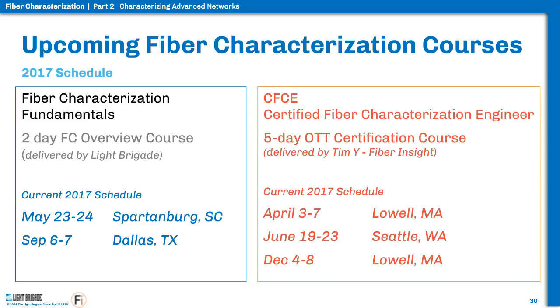I could also choose to do the ORL measurement using my OTDR and not an ORL meter. So I could skip the ORL measurement in a purist sense. I could run my OTDR measurement and get ORL and reflectance data. Keep in mind that with an OTDR, you're able to get ORL values, especially if you use launch and receive cables. The point here is you're able to see and measure the loss and the reflectance of each distribution frame connector pair. So you can do that on an OTDR.